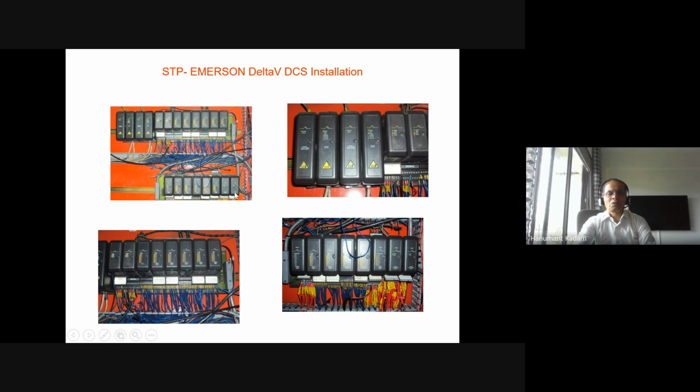IO carriers, IO capacity, how it is extended. This is what is shown in these pictures, various pictures. You can see here various cards, terminations, because DIDO has some different color cables, AIO some different colors, with the ferrules showing these ferrules. You understand, for identifying from which area it is coming, from which devices it is coming.